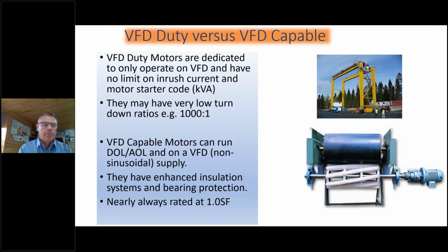VFD capable motors, which means that motor can run either across, if you see in my notes there, it says DOL, AOL. The DOL stands for direct on line, the AOL stands for across the line. So that means that motor can be used with a normal motor starter, or it can be used with a VFD. VFDs will add a little bit of heat to a motor, so there are some other factors that are put into that.